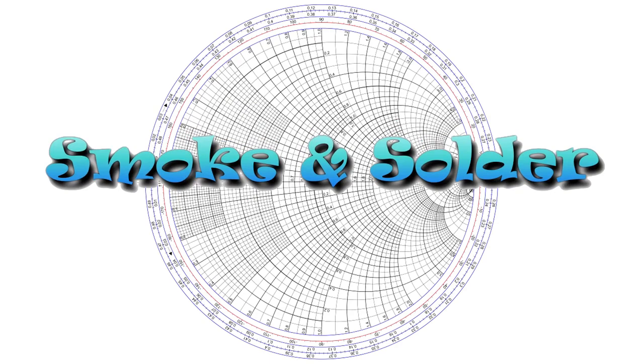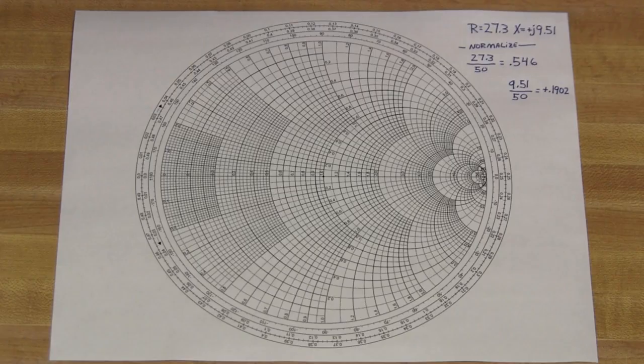A few weeks ago, we looked at Smith charts, and I told you we would revisit the subject and actually do something useful with it. Well, that's what we're going to do this week. We're going to show you how to plot VSWR on a Smith chart. We're going to start with some values I got from measuring two 50 ohm terminators with an antenna analyzer. I measured a resistance of 27.3 ohms and a reactance of a positive 9.51.